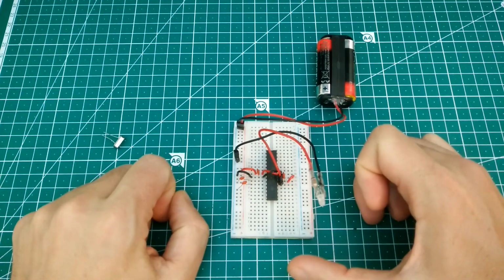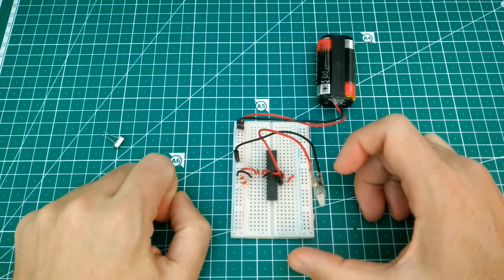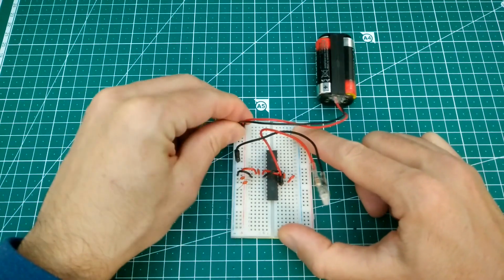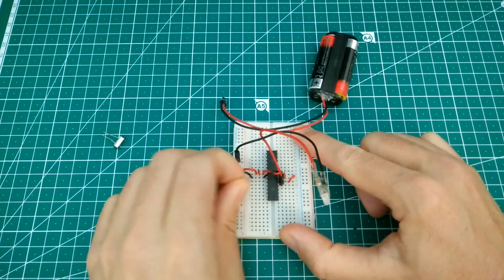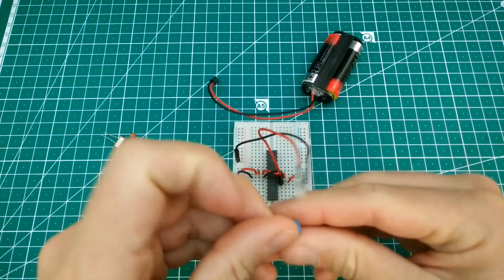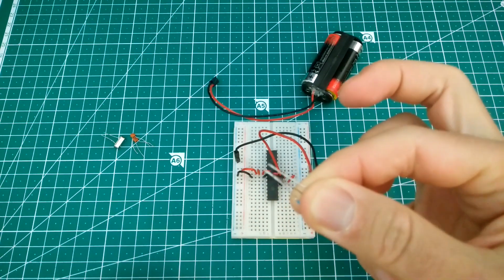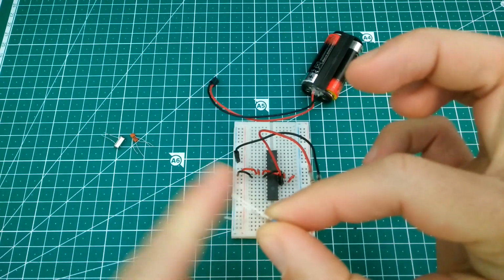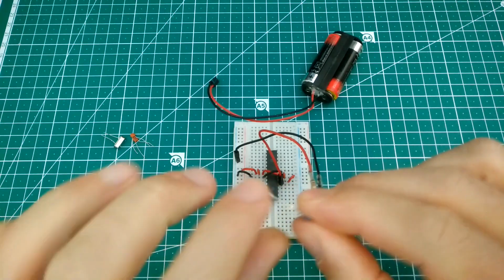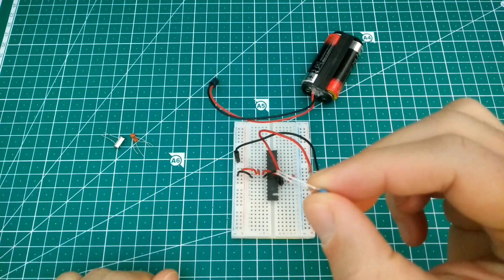Now, I'm going to show you how you use a ceramic resonator here, because it is a direct replacement for the crystal. So first, let's just take the power off, and we need to take the two load capacitors off. There are three legs here. The side ones are as if they're the crystal legs, and the third middle leg, which I already have extended because it's going to go to there, is as if the other legs of the load capacitors. It goes to the ground.